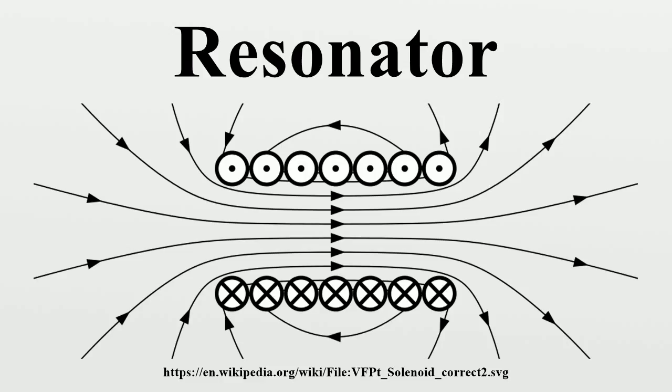Examples: the cavity magnetron is a vacuum tube with a filament in the center of an evacuated, lobed, circular cavity resonator. A perpendicular magnetic field is imposed by a permanent magnet. The magnetic field causes the electrons, attracted to the positive outer part of the chamber, to spiral outward in a circular path rather than moving directly to this anode.